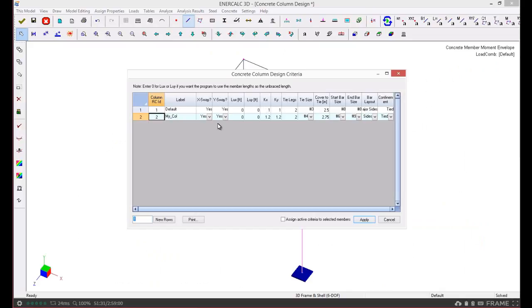column design criteria and see about increasing the bar sizes that were allowed to be considered, or changing the bar layout, or it's possible that my little sample model here is just overloaded and we might actually need to reconsider the column sizes that I've chosen.